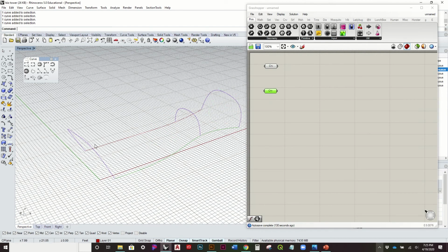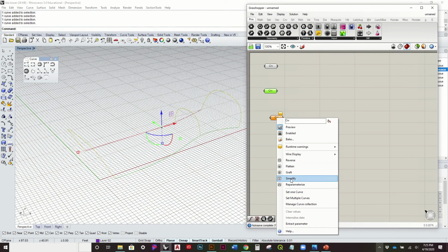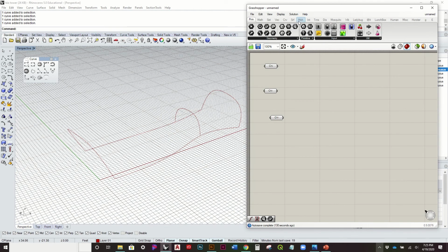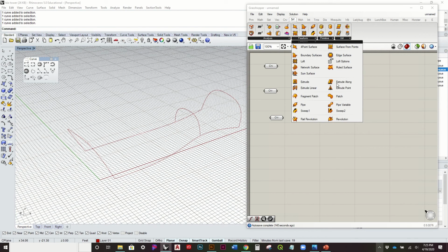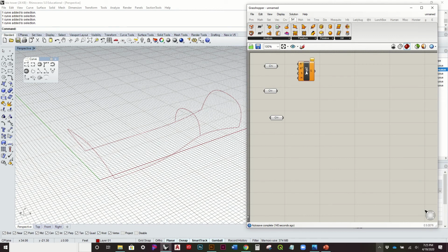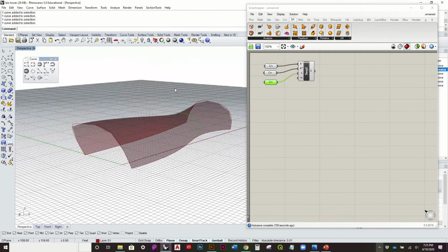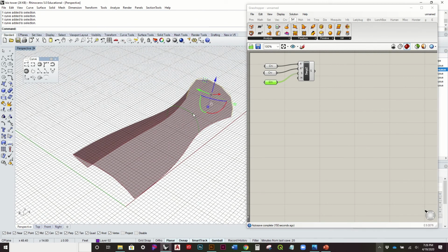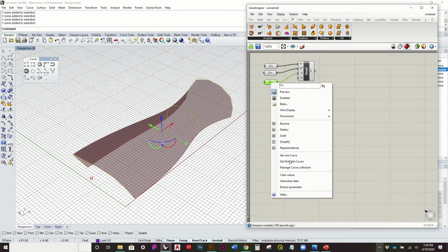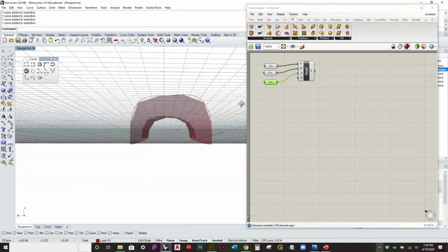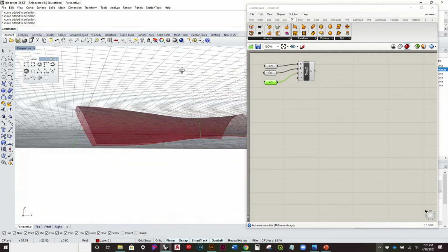Let's just go ahead and show it like this. If I select them like that, say set multiple curves, let's see if we can create a surface from that. So freeform, Sweep2, so our first rail, our second rail, and our section or profile curve, right? You want to definitely make sure you do that in order. If I had selected it this way, say set multiple curves, oh, it looks like it's okay. So it looks like I did it in the correct order anyway.